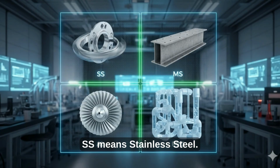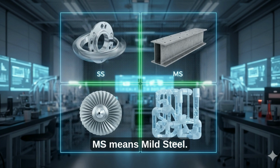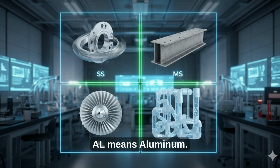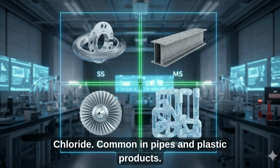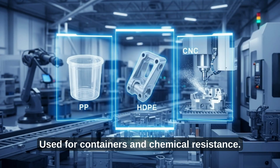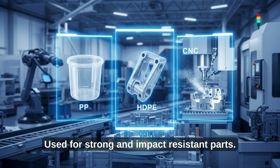SS means stainless steel, used where rust resistance is needed. MS means mild steel, used for general purpose and structures. AL means aluminum, used when lightweight matters. PVC means polyvinyl chloride, common in pipes and plastic products. PP means polypropylene, used for containers and chemical resistance. HDPE means high-density polyethylene, used for strong and impact-resistant parts.